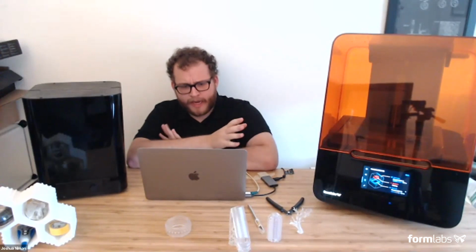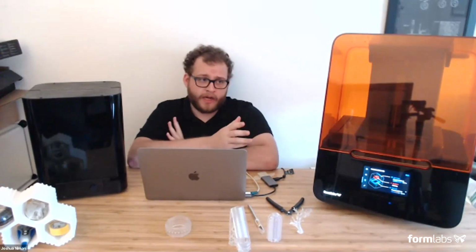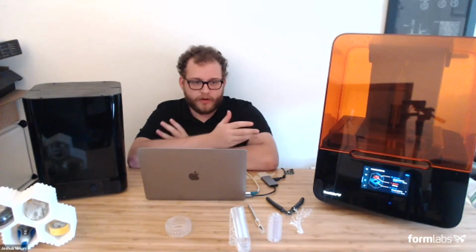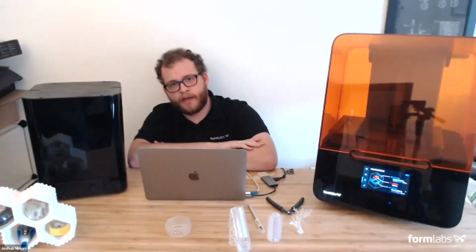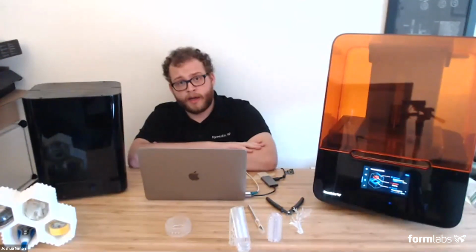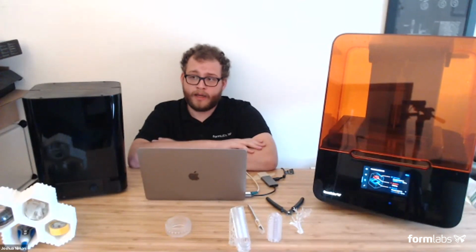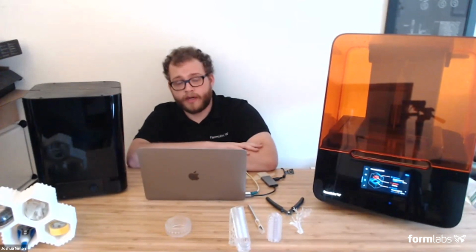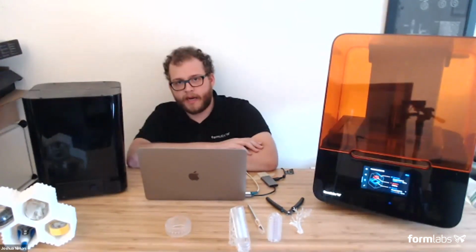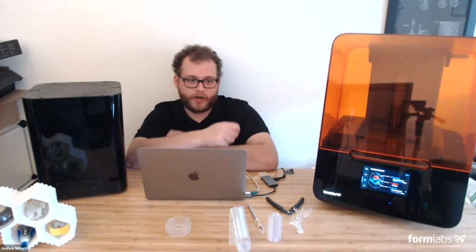And so we launched Elastic because we wanted to expand to a more silicone-like, a 50A short durometer material that was soft. It was suitable for lots of things like medical modeling, anything really that you'd use silicone for. And then we went back, and with the lessons that we learned from that, we looked at our flexible resin, and we thought we can do a lot better here. We can make a material that has that 80A Shore hardness and is suitable for those harder rubber applications, keeping in mind what a car tire feels like, but that has much more resistance to fatigue, is much stronger, is much more suitable for applications where you're going to be flexing it over and over again, or you're going to be trying to wring it out.